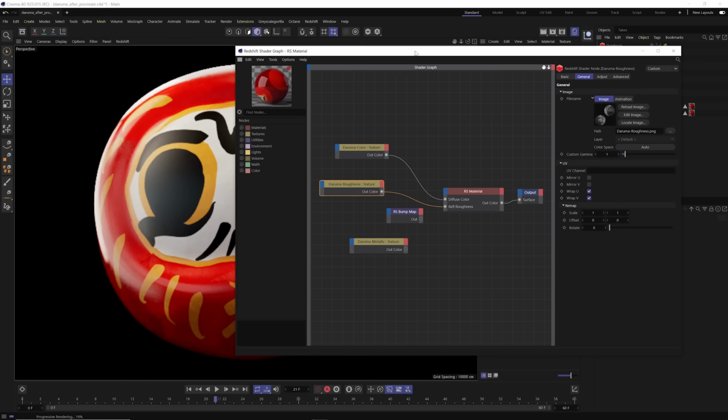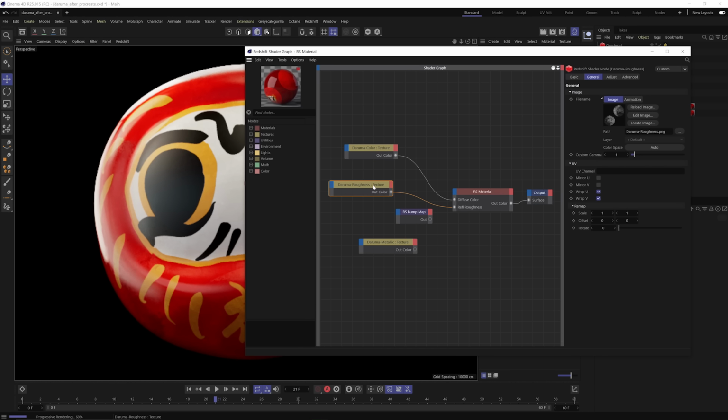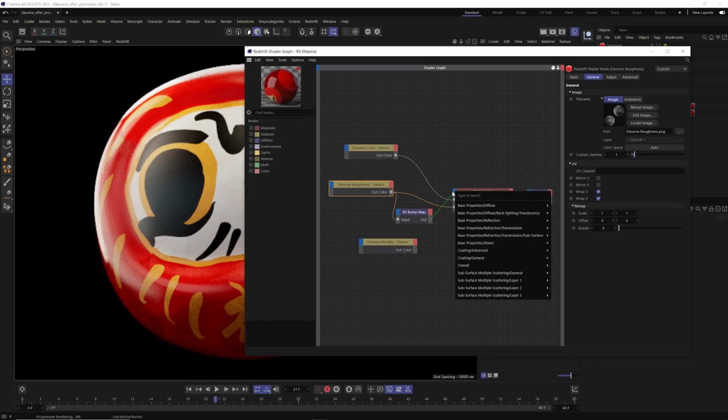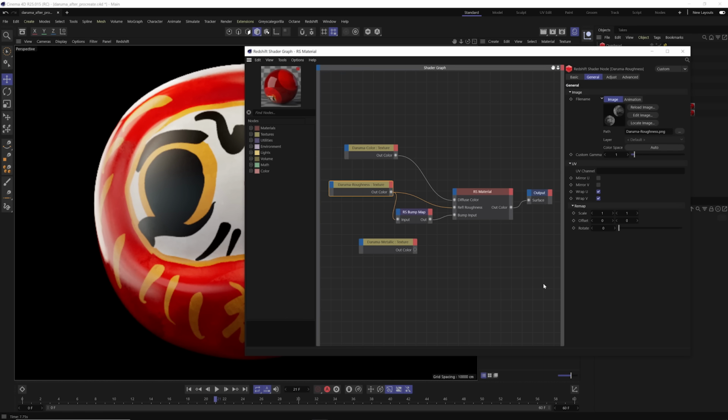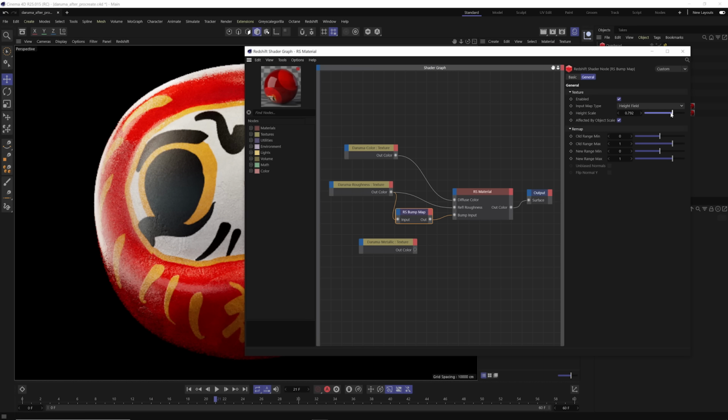And just to make up for the fact that you can't actually create and export out your own bump or normal map out of Procreate, at least in this version, I just went ahead and pumped in the roughness into a bump map, and I'm just using the roughness for the roughness of the reflection as well as a bump map. You see that adding that bump map actually helps out a lot. And actually one other thing to consider is just going into Procreate and on that color channel, just using grayscale values and grunging it up and create your own bump map that way.